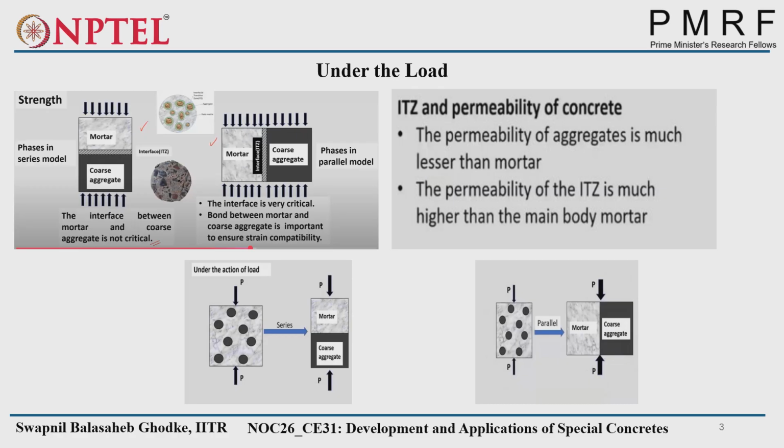If the pores are interconnected, then permeability happens. If the pores are not interconnected, permeability will not happen. But there is a possibility for hazardous material from outside to get into the concrete and affect its durability. So permeability is more about interconnected pores, while simply pores or voids reduce the strength of the concrete.